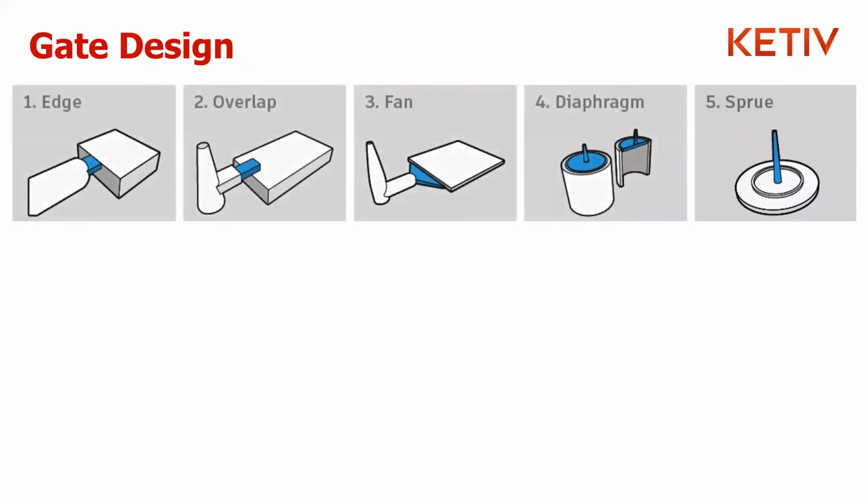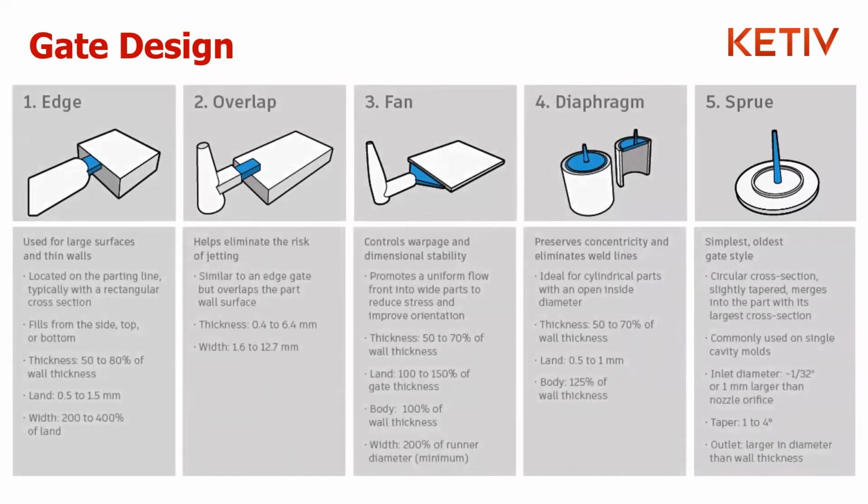manufacturing. And this next section, just feed system and gate design, is also another important thing to explore if you look at the functionality of them, developing a mold and process. The feed system and the cooling are quite often overlooked. We tend to use guidelines. We have guidelines in mold flow and guidelines in the industry. And guidelines are kind of like comfort food. It tastes good initially, but it might not be good for you long term.